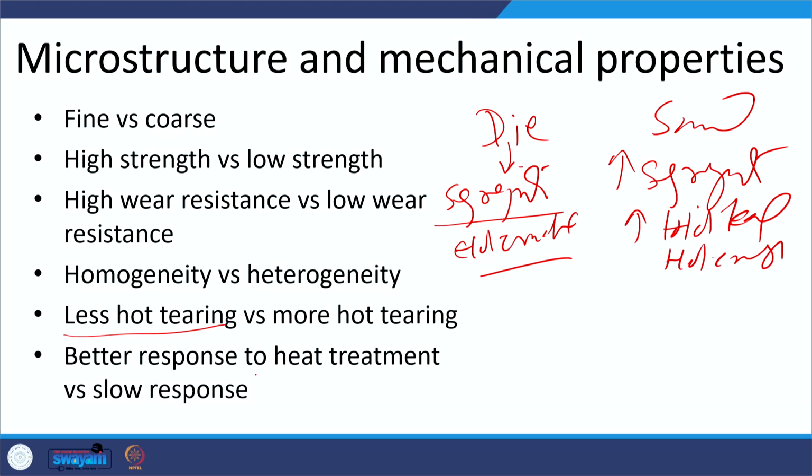And then the response to heat treatment. It depends on the kind of metal system, but if it is about non-ferrous metals, T6 is one of the common heat treatments, or in case of ferrous metals it is austenitizing followed by imposing a suitable cooling rate, which may be slow, medium or fast cooling, for hardening, normalizing or annealing as per the case.